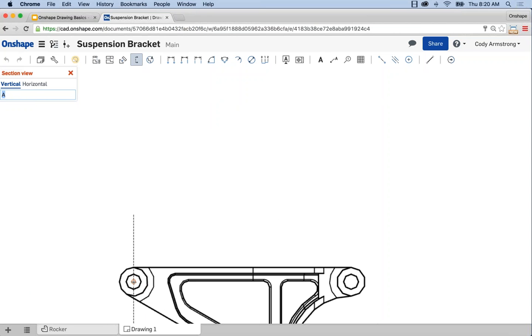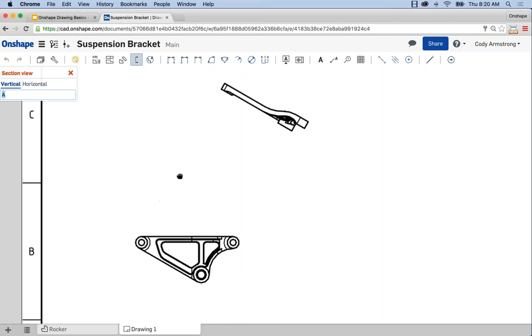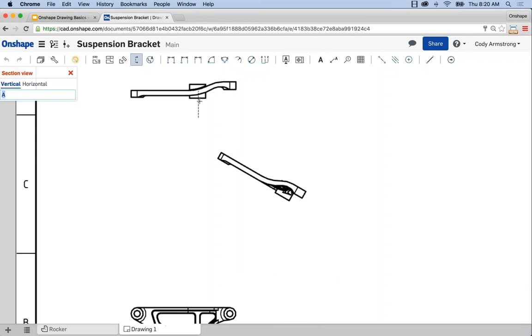The reason I bring this up is those cues, here's the square, here's the triangle, they mean something. The square means the end point of the edge or line. The triangle means the midpoint, so you can snap to the midpoint of any edge or line. And then the circle means center point. So you do get some visual feedback as to what you're attaching your reference to.